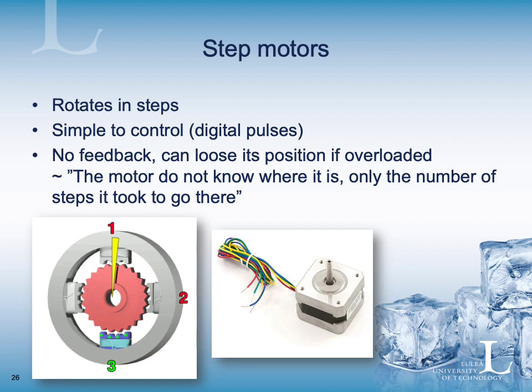Step motors are also a special type of electric motors. Normally, when we talk about electric motors, they are rotating with a certain RPM. But a step motor, you can instead make rotate 60 degrees and stop there. For instance, if you have a 3D printer, you have seen all the step motors that are used for controlling all the different motions in X, Y, and Z, and also the extruder of the filament. These are very good if you want to have slow rotational speeds with a super high precision.